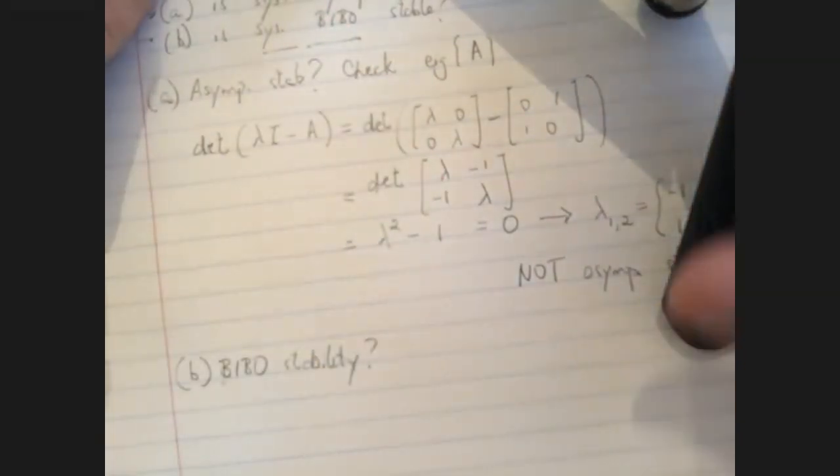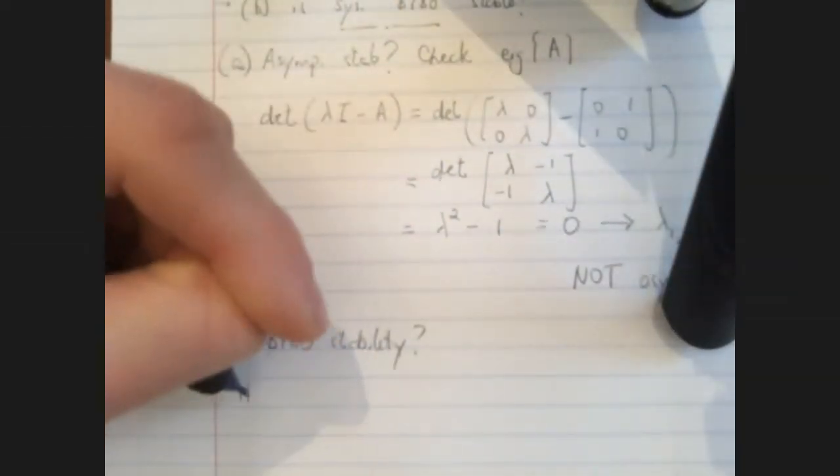For that, we would check the transfer function. I'm given A, B, C, D right there. The transfer function, let's call it H of s, is C (sI minus A) inverse B plus D. In this case, D was 0, so it's just that.